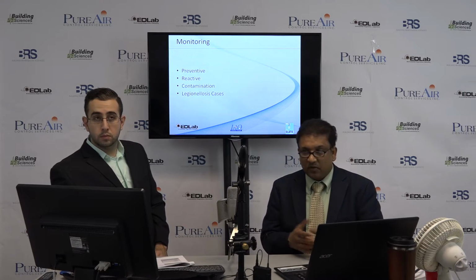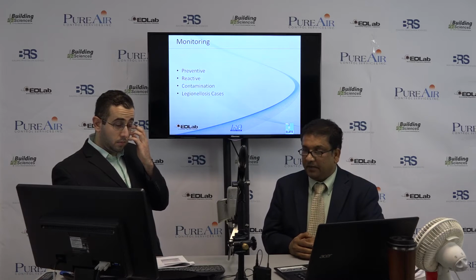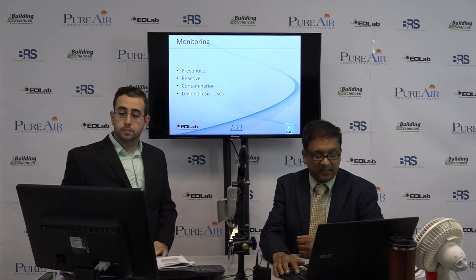So in a reactive approach, you can also derive some information from ASHRAE 188 on how to address them. Contamination control is also initiated based on that information, and with the Legionnaires' cases from the local health department, in collaboration with them, you can understand what is more important in order to prevent those diseases in that particular area.